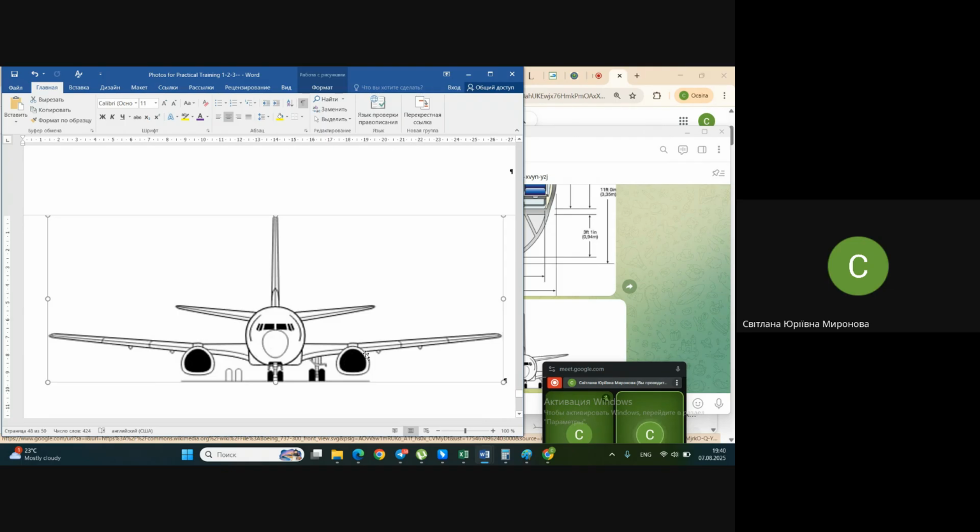Altogether, four engines may create your necessary thrust, but in this case you need to remember that the general weight of four engines with their nacelles, pylons, control systems will be a bit heavier than two engines. So it's also not an ideal decision. As I already said, there is no best decision in aircraft design, not the only best decision. It's dozens of decisions and each of them has advantages and disadvantages.